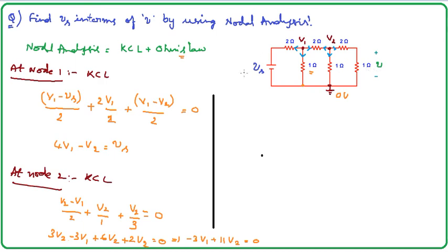My problem, which has been given, is that I need to find Vs in terms of V. According to Ohm's law, the current passing through the 1 ohm resistor, let me consider this as I. So I is equal to voltage V divided by resistor 1, which is equal to V. So the current passing through this resistor is I, that is V, and the same current is flowing through this 2 ohm resistor also.